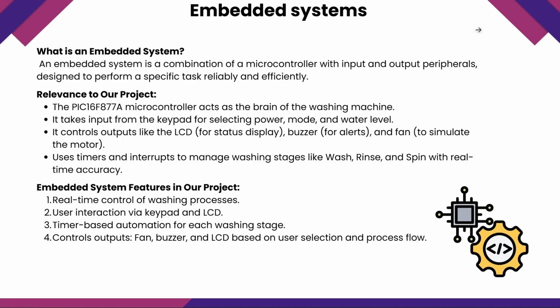It takes input from the keypad for selecting power, mode, and water level. It controls outputs like the LCD for status display, buzzer for alerts, and fan which simulates the motor. It uses timers and interrupts to manage washing stages like wash, rinse, and spin with real-time accuracy.